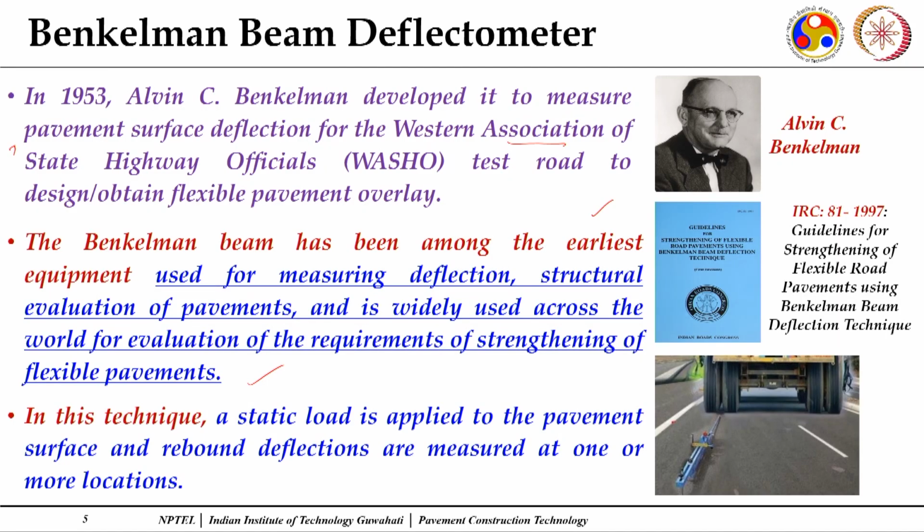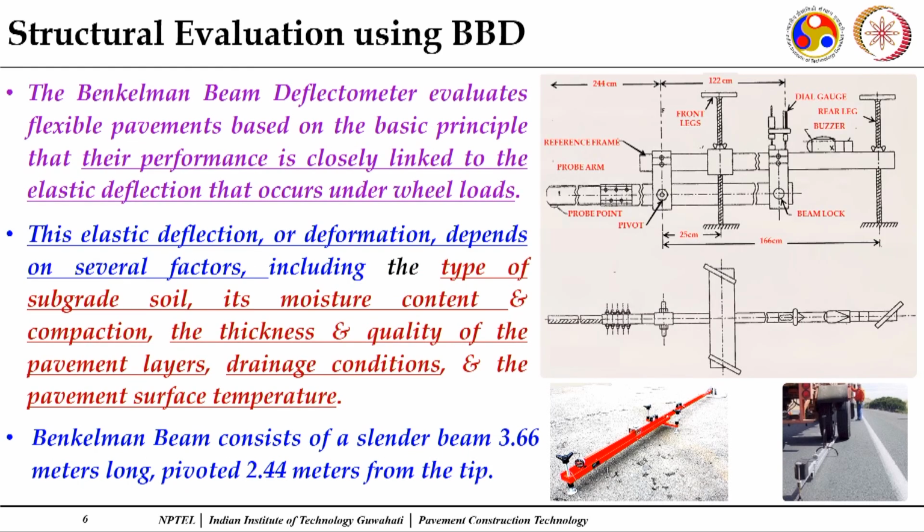In this method of structural evaluation, a static load is applied to the pavement surface and rebound deflections are measured at one or more locations with the help of a Benkelman beam. You can see there is a vehicle with dual tires on one side. This is a beam whose probe is inserted between the dual tires, and then the deflection measurements are made. We will discuss them in detail.